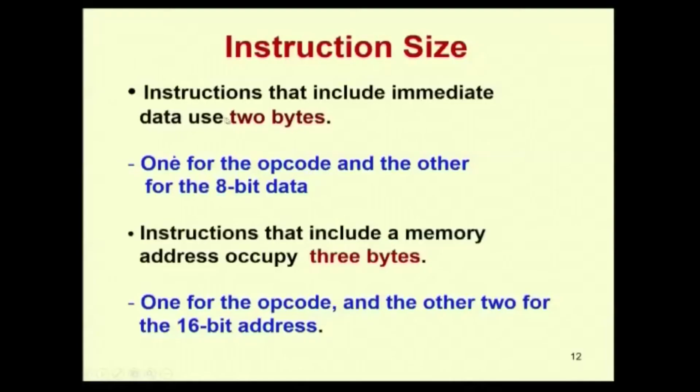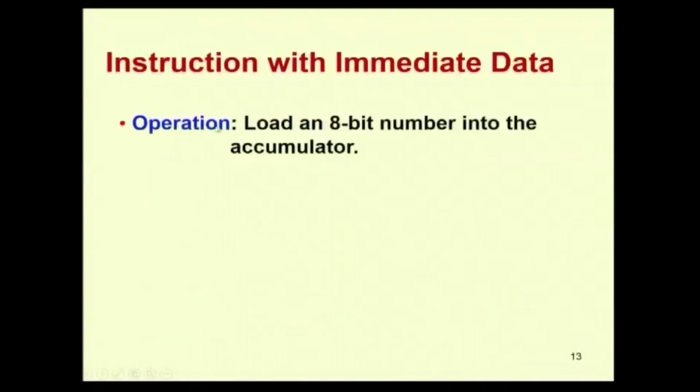As I mentioned, there can be single byte, 2 byte and then 3 byte instructions. The instructions corresponding to memory operations, where you have to mention the address of the memory location, all involve a 16 bit address. The memory has to be represented by a 16 bit number, therefore, they are all 3 byte instructions. For example,